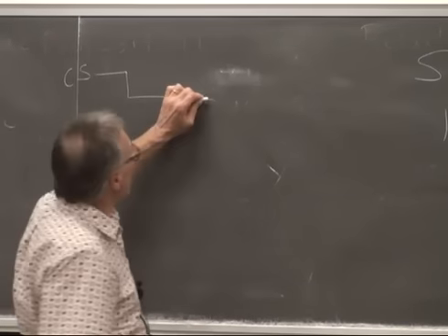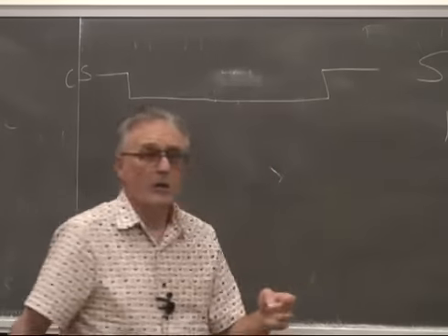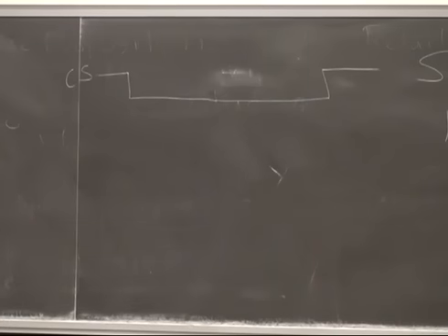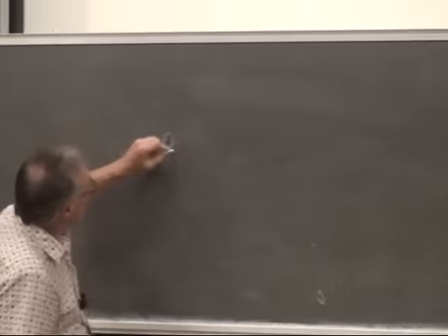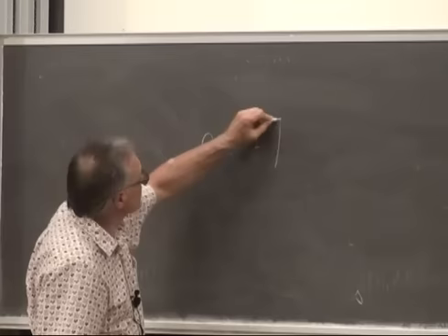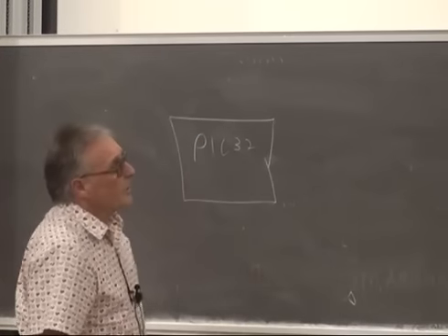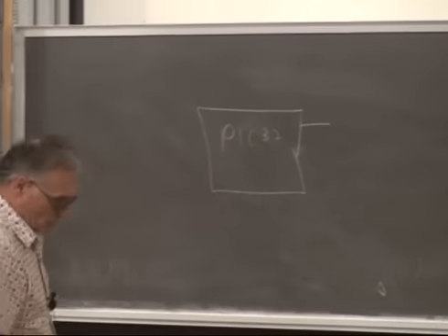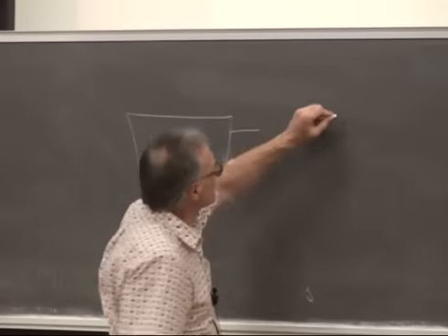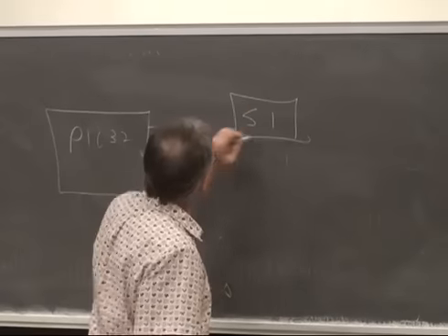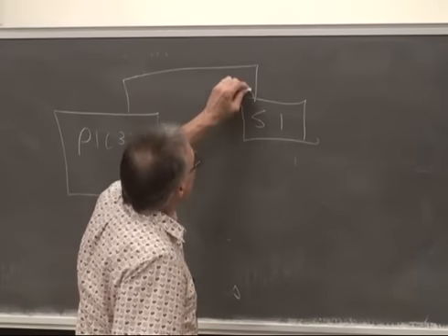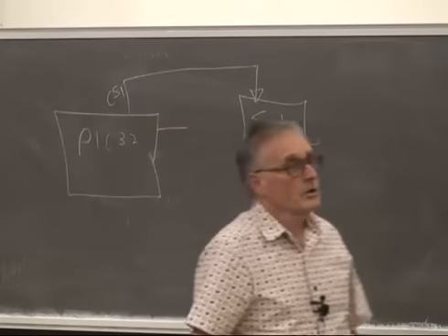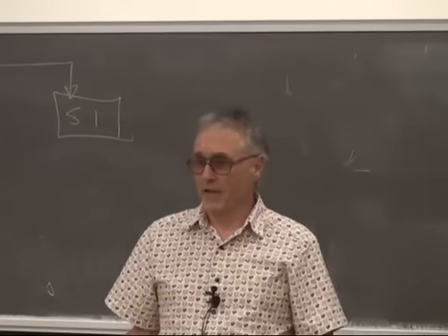Dropping the chip select line is going to be a signal from the master to the slave. The master in this case is going to be the PIC32. When you drop the line for the chip select, you start the transaction with that device.